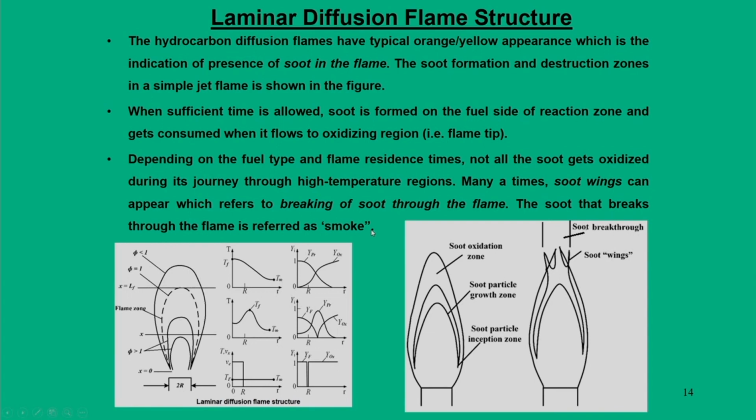Another significant part of this flame is soot formation, the formation of soot in a flame. We already said that when you see the flame surface below phi equal to 1, all of it has an equivalence ratio more than 1. That means they are rich in fuel, but they do not find sufficient oxygen or oxidizers. So, this causes some unburnt fuel particles to remain.